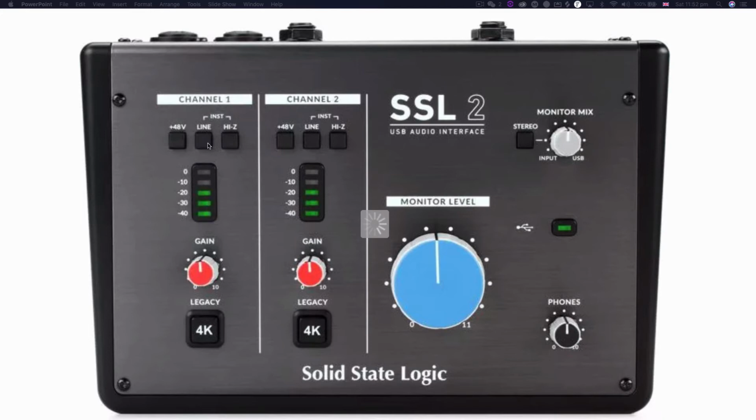Above the meter, you see three buttons here. The right two are a switch. The default setting for most audio interfaces is that they're always looking for mic level. But just in case, guitarists, for example, have their own signal processing going on, and sometimes they send line level directly to the audio interface, so they don't need a preamp anymore. You can just press that and tell the audio interface, okay, I'm looking for line level now, not mic level.